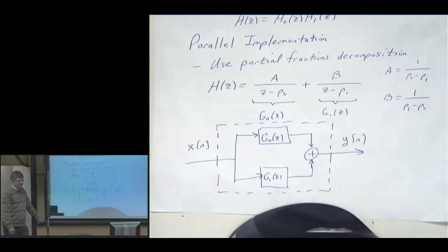Well, I was just saying, if you multiply everything out, then you end up getting z to the negative 2, and then you end up having more initial conditions to keep track of. Well, I still have an initial condition here, and for this case of a second order transfer function, which realizes two parallel first order filters, I still have an initial output here and an initial output here. Still two initial conditions. Oh, okay.